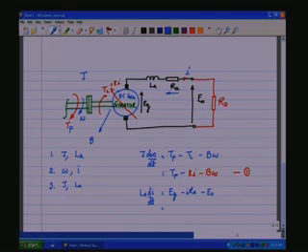Now, Eg is given by the cross-linked variable, which is k omega. So, you have k omega minus i RA minus i R naught, all expressed in terms of the state variables.